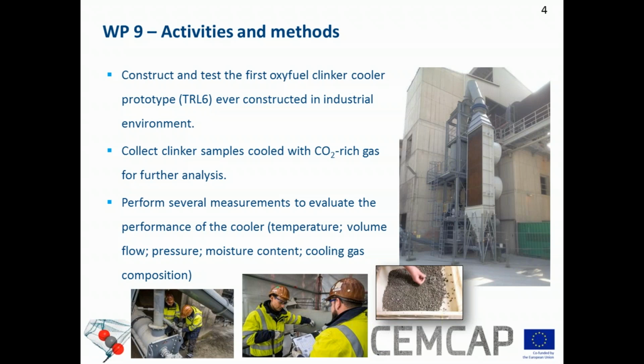The trials were performed in a Heidelberg Cement plant in Hanover, and the cooler was designed and constructed by EKN. We also collected clinker samples cooled with CO2-rich gas for further analysis. The clinker samples were later analyzed in VDZ's laboratories. Moreover, we also performed several measurements to evaluate the performance of the cooler. Among them are the temperatures, volume flows, pressures, moisture content, cooling gas composition, and so on.